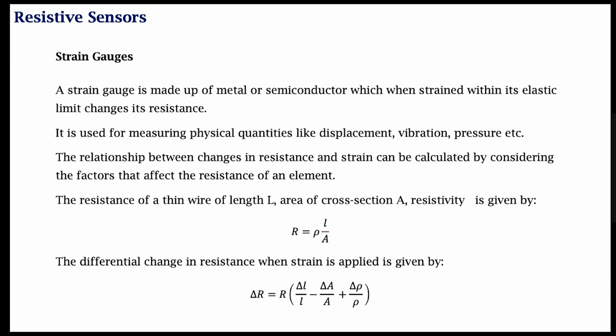So when the resistance changes and when we measure the voltage across that resistance, the voltage will also be changing. And it turns out that we can indeed calibrate the force or pressure change to the voltage change. We can come up with a linear relationship between these two quantities, so that if I measure a change in the voltage, we can try to understand what the corresponding applied force or pressure was.